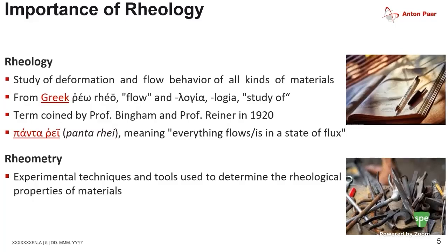So as I said, rheology covers a vast range of materials. But rheometry, which covers various types of techniques or systems, consists of experimental measurements. You can use a rheometer, a viscometer, or a capillary design setup. In essence, we just poke and prod at the material to see its response back and get a rheological understanding of the material under different stresses, strains, temperatures, or even pressures.